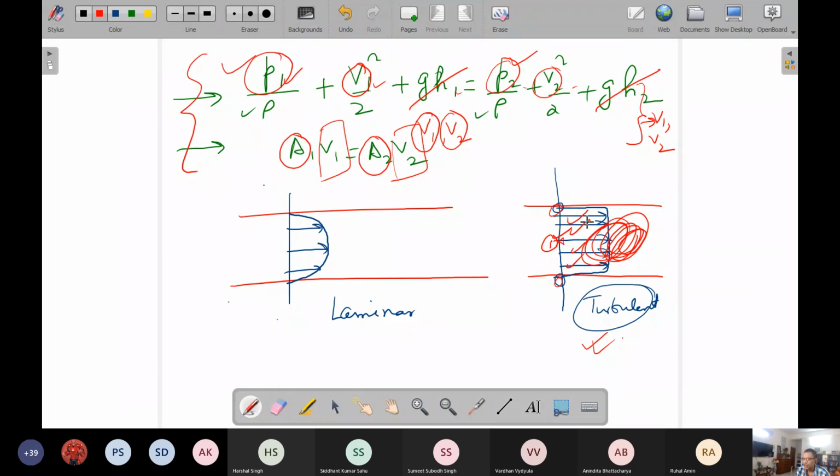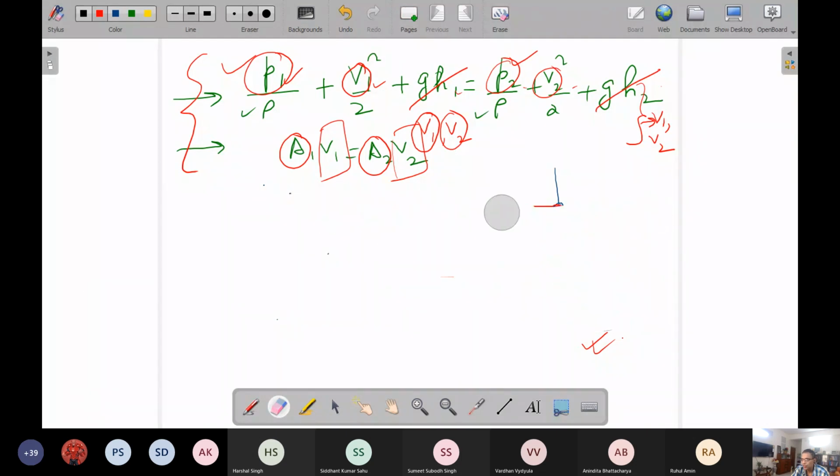Of course, there are several ways of accommodating this anomaly between the use of velocity at a point and velocity at a section, and how that is accommodated. Even in undergraduate fluid mechanics classes, it is done in a little bit of a gross sense, but it is done correctly. There are two corrections made to the equation, I mean the so-called Bernoulli's type of equation.